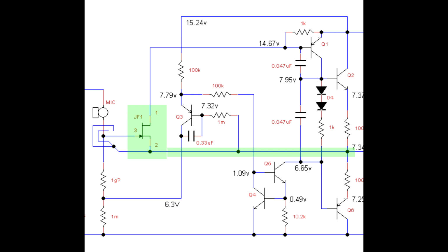So that means the source goes up, which means the biasing of the FET is changed and the FET will conduct less. So it's negative feedback. It's a very, very clever way to use the FET in both a plus input and a minus input. This might take some thinking on your part to figure out how this actually all works. But it's a very clever circuit. It's a minimal number of components, and it's doing a lot.